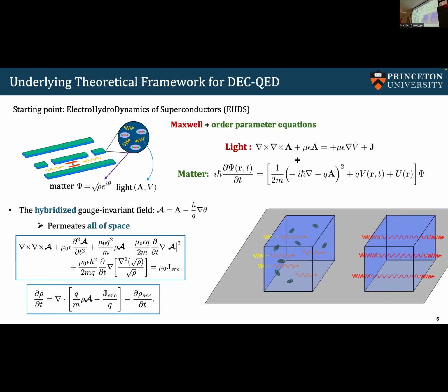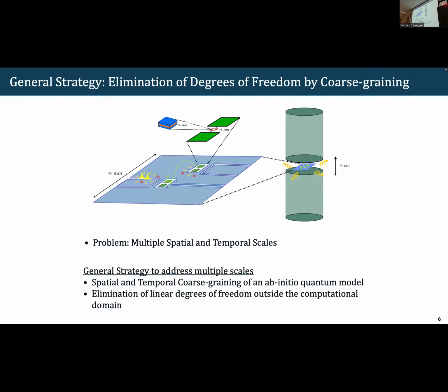Right. So besides the need for choosing a suitable formulation for superconductivity that can capture crosstalk, correlated noise, and hybridization, another major challenge in modeling electrodynamics of circuits, as I'm sure everyone that has to actually run the simulation will know, is just the multi-scale nature of the device, right? Because you have feature sizes ranging from nanoscale, being the junctions, all the way to millimeters and up to centimeters if you try to take into account the packaging case altogether.